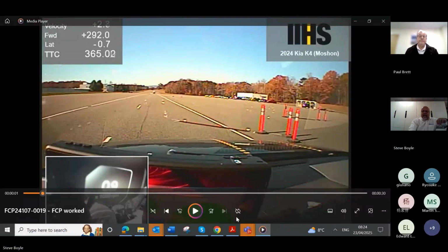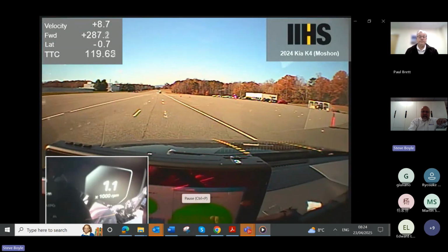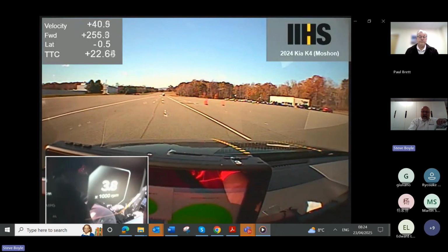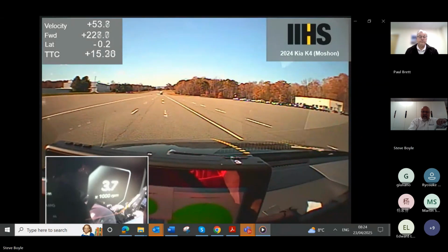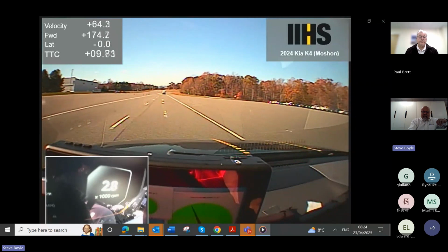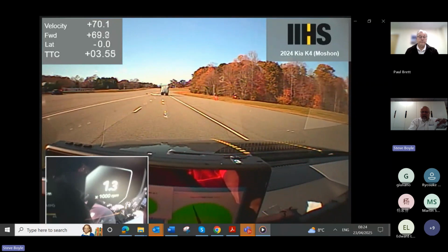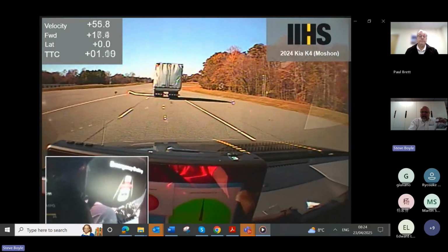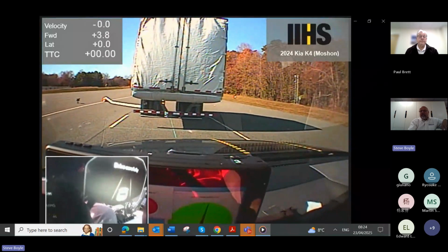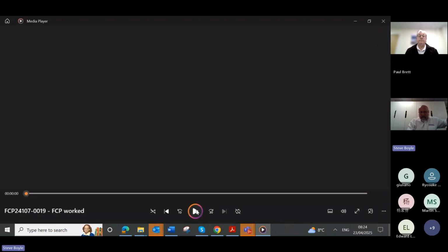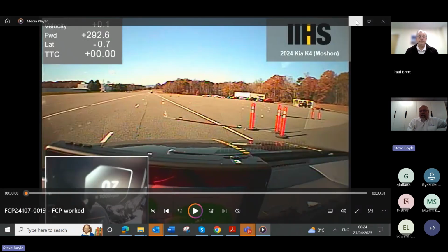Yep. So this is one of the vehicles that we used as a test at the time. 70 kph. So you can be at 70 kph driving at the target, and the forward collision warning will activate. At the bottom of the screen, we have this green and red yes or no. So you've got the forward collision warning. Well, sorry, this shows stop. This will show you stop, indicating stopped. That was the A/B stop against the vehicle target there.